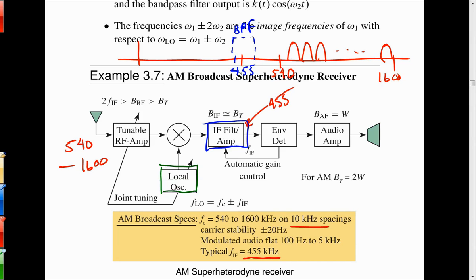It's either AM modulated, double sideband, or, as we're going to start on today, angle modulated. So it's in the argument of the cosine, but it still doesn't matter. The trig identity still applies. The trig identity of cosine times cosine is going to produce a sum and a difference frequency. So the mixer output will be a sum and a difference.